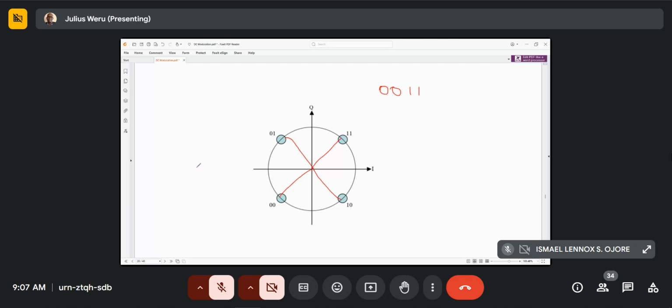You're going to find that the coherent receivers perform better, but I'm trying to look for an intuitive explanation of why it's important to use coherent where you have a choice, of course. With PSK you don't have a choice, you have to be coherent, because our message is carried in the phase, so there it's very important. So I think your question is, where you have a choice, why would you?